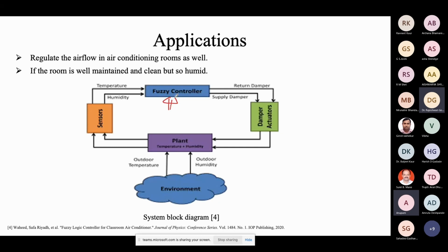If it is digital, whatever resistance or capacitance are there, they may change as time passes, right? So older controllers like PID may not cope with the changing environment, the changing condition of the plant, right? So fuzzy has some functionality by which it can adapt. However, PID also has it, but fuzzy has a better way, right?